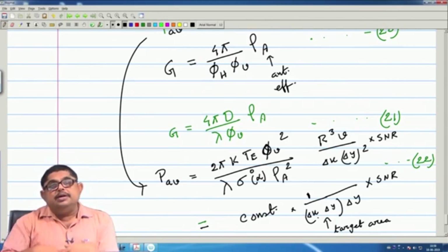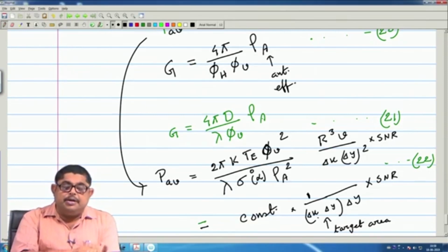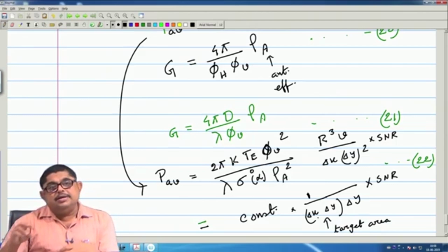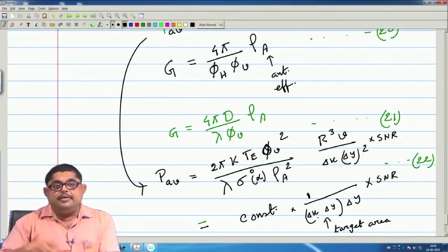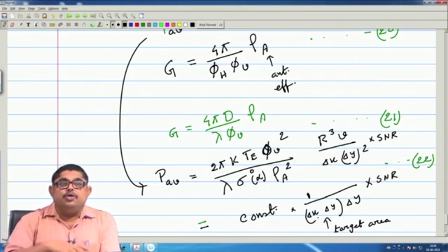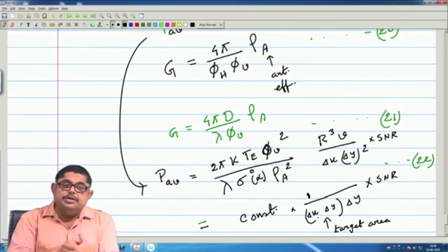If you have infinite power, definitely you can go on reducing the antenna, but with limited power handling capable transmitters, you cannot go on reducing D. So, from an engineer's perspective, in the application at hand, you fix a particular antenna diameter or length, the maximum dimension of the antenna, and then your cross range resolution cannot be better than half of that.